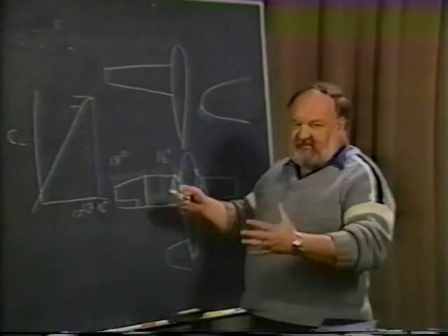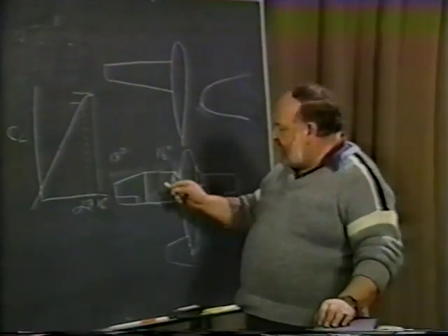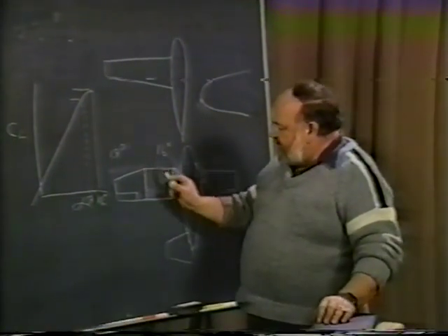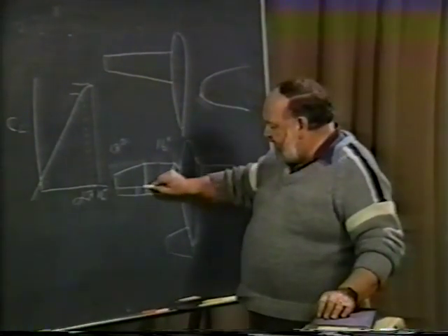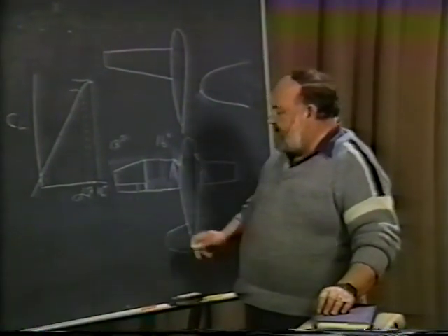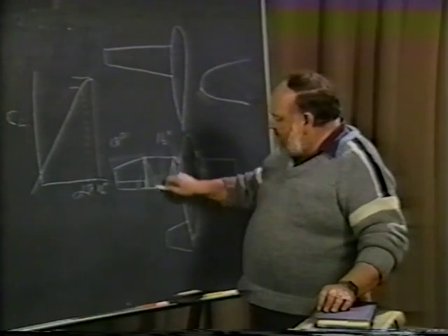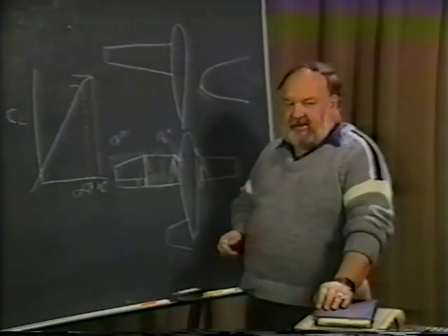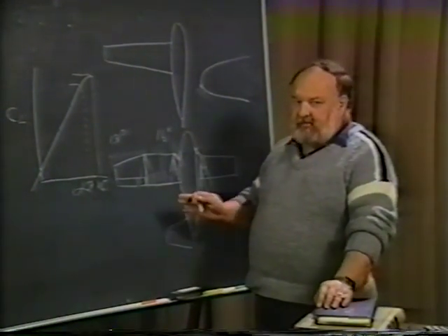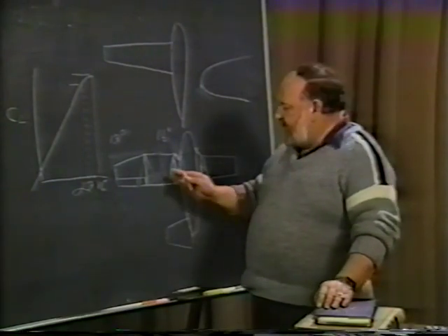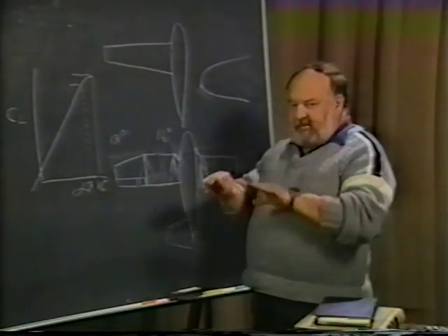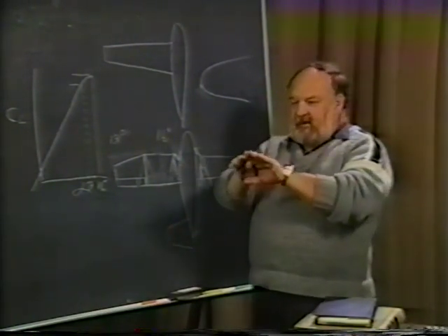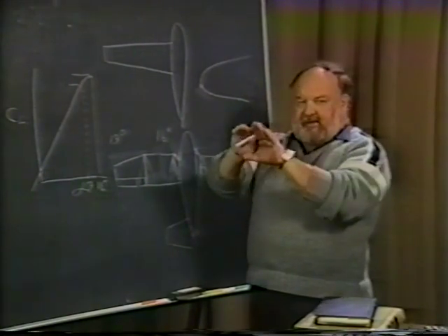It looks like a nice fancy little layout, it has good aesthetics to it, but if this break here is too far outboard, and if it's all the way out to where the ailerons themselves begin, then you're going to be causing a flow separation to begin quite a ways outboard, and it's always dangerous because it's not that easy to make an airplane fly through very smooth air and pull it up and stall it without any yaw whatsoever to it,